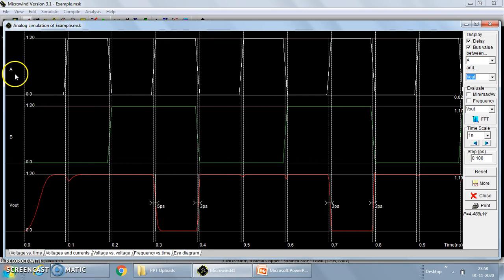And that's why the frequency of clock A and clock B should be different. Either it can be half of the other or double. Either will work, so that all the 4 combinations will be covered.